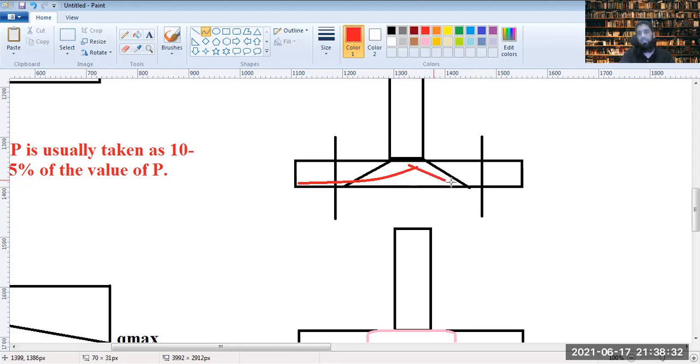So likewise, you have the same situation on this face. So we usually need to provide, because below the column we already have the reinforcement here of the rings from the column, the reinforcement at the bottom of the footing. So that is the tensile reinforcement.